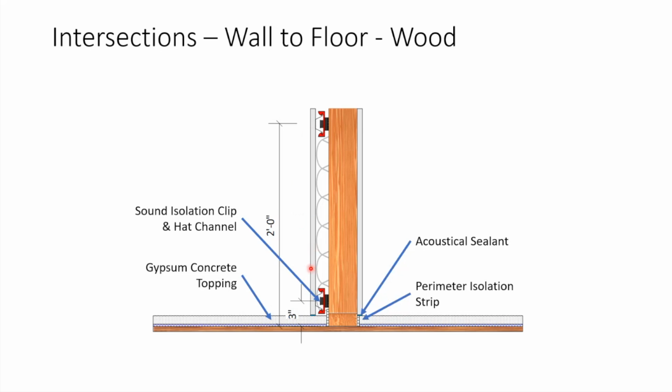We got called out. And when we went out, we asked them to remove the drywall so that we could inspect the wall behind it and see if there were any installation issues. They went to remove the drywall, but they couldn't. Turns out it was embedded in the gypsum concrete. The gypsum concrete had flowed around and encapsulated the bottom of the drywall. So then you had this sort of rigid connection path through. So we want to make sure that we don't do that, that your drywall is decoupled, isolated from your gypsum concrete. Also, your gypsum concrete is typically decoupled from your structure. So you want this sort of bathtub isolating that, and then you want to make sure that your drywall floats separately, so it can freely float on your clips or your resilient channel or whatever it may be, right?